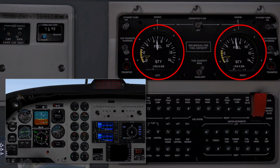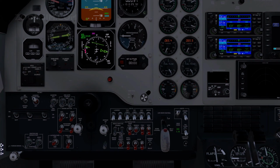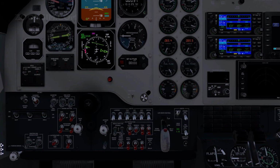Fuel quantity, instruments, check. Annunciators, out, considered. Transponder, on. The transponder identifies the aircraft on air traffic control radar. It emits a code identifying signal in response to an interrogating received signal.